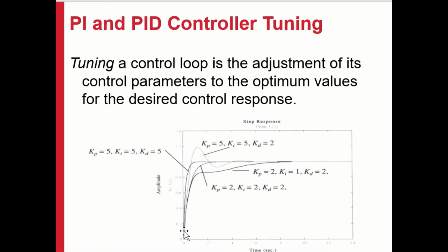And the type of thing we're looking for in terms of performance is that the transient response can be as fast as it possibly can be, fast rise time, but very little overshoot and very little undershoot. So it comes up, holds the line, gives us a nice transient response. This one has got too much overshoot, too much undershoot. This one's a bit slow coming up here.